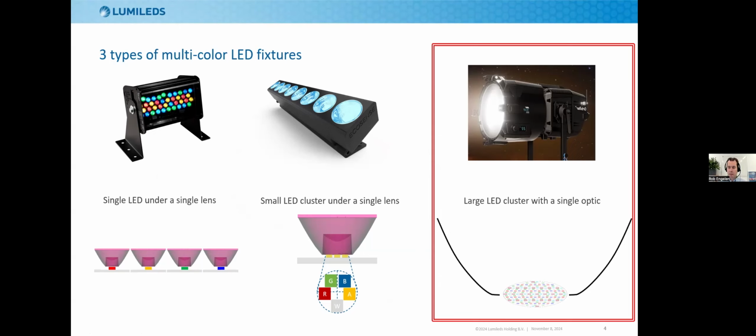Around this LED array is then, I sketch schematically here a reflector, but it can also be a more complex optic like above, where you can still do some zoom, change the beam diameter and such. But in essence, it is this. So why is this a big thermal headache? Because all the energy is concentrated to this 20 or 30 millimeter array, and you need to dissipate that heat in order to keep the array cool, or at least not overheating.